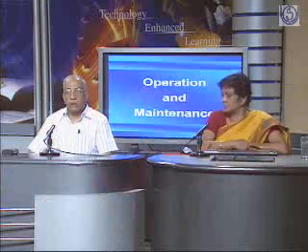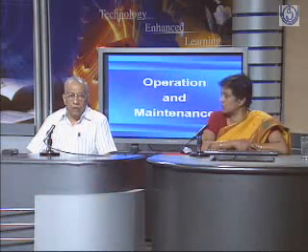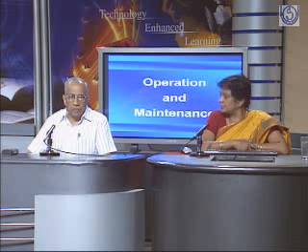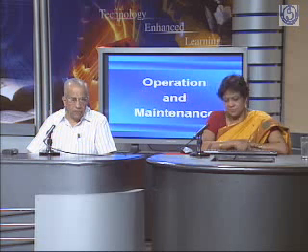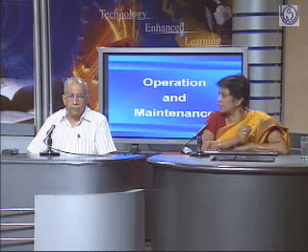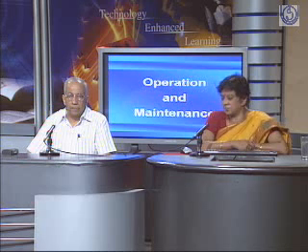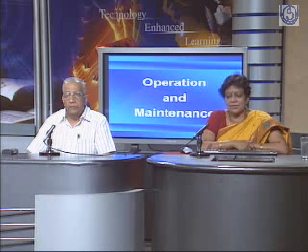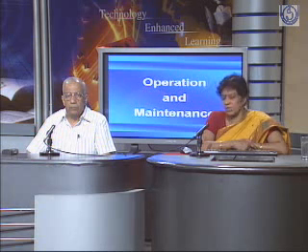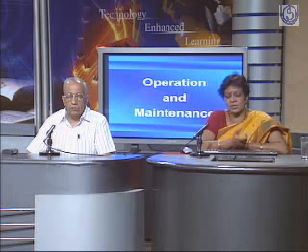Only 3 or 4 customers are affected with that transformer. Now, the bigger transformer has been replaced by maybe hundreds of transformers. So, if 2 or 3 fail also, then the number of customers affected will be much less. Anyway, the customer is definitely important, and we advise that you should keep an inventory of the small capacity transformers, and it's quite easy to erect because it is a single transformer with a single bolt, so it's much easier to erect a new transformer.